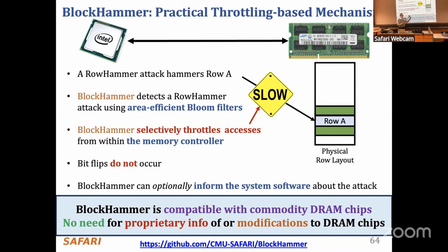This is okay in this particular case, because what we're going to do is say that if the counter is greater than some threshold, this row is potentially going to cause a bit flip. Now, if the counter is incremented by only that row, you have an okay and exact count, depending on the limitations of the counter, etc. But if the counter is incremented by two different rows that are being accessed, you have an inflated count, right? And that inflated count may cause you to wrongly detect a row to be an aggressor.